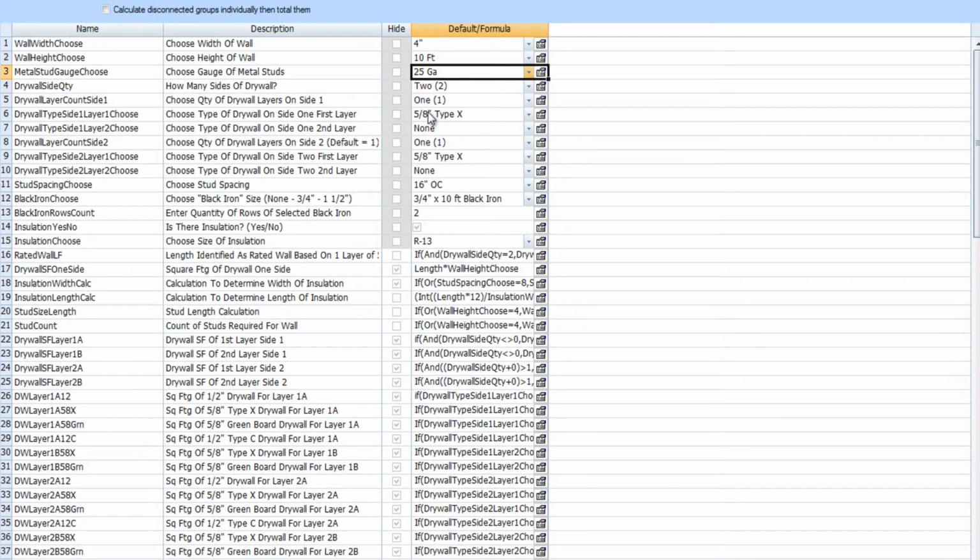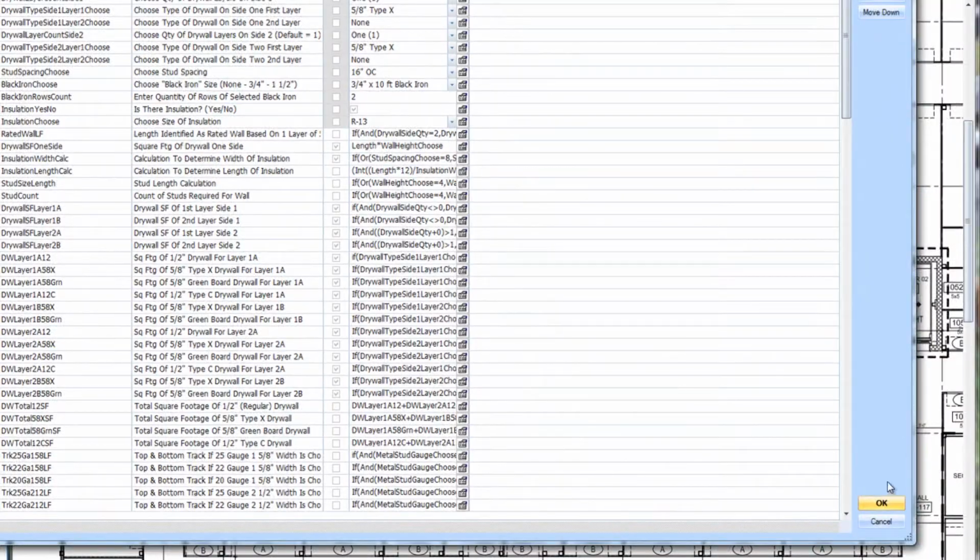I usually do the walls that are not the norm for the project first, so the plans are marked when it is time to do the walls that are the norm. In this way, there is less chance of estimating a wall with the wrong configuration.